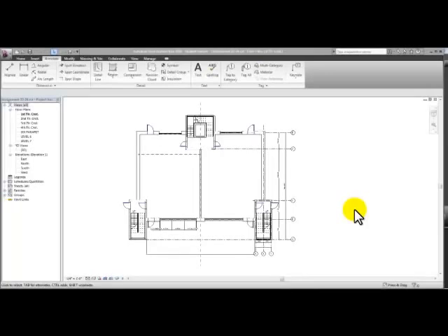Once a project is submitted or issued for owner review or out to bid, if there are any revisions that need to be made to the drawings, we document these changes by drawing a revision cloud around those changes. The revision cloud is marked with usually a number in a triangle, and the number and name and date of the revision is documented in the title block. It keeps track of changes made to always update the drawing for production and for the as-built drawings at the end of the construction.